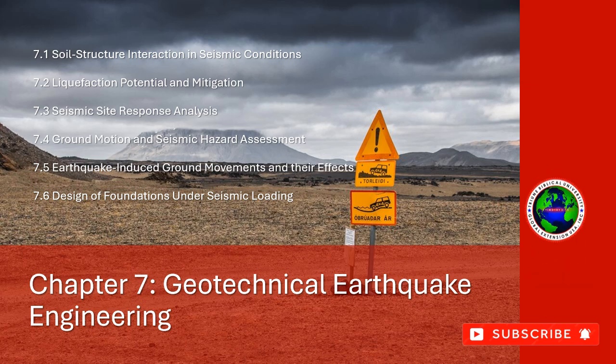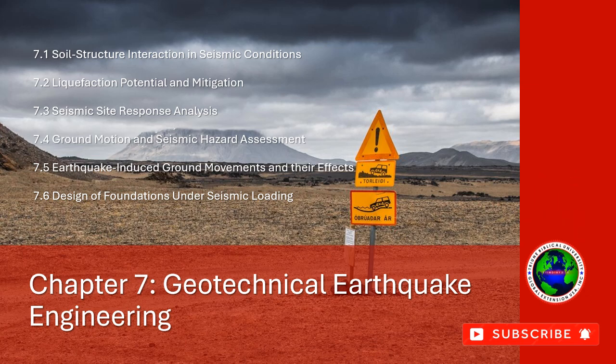structures. Liquefaction primarily occurs in saturated, sandy soils that are subject to intense shaking during an earthquake. Understanding the potential for liquefaction and employing mitigation strategies is critical for ensuring the safety of structures in earthquake-prone regions.